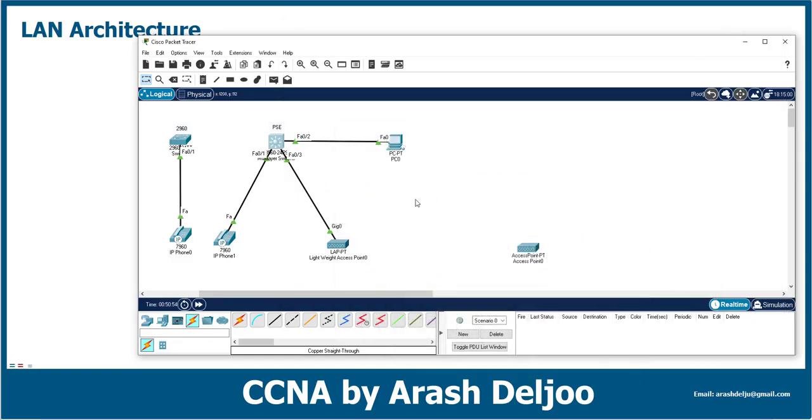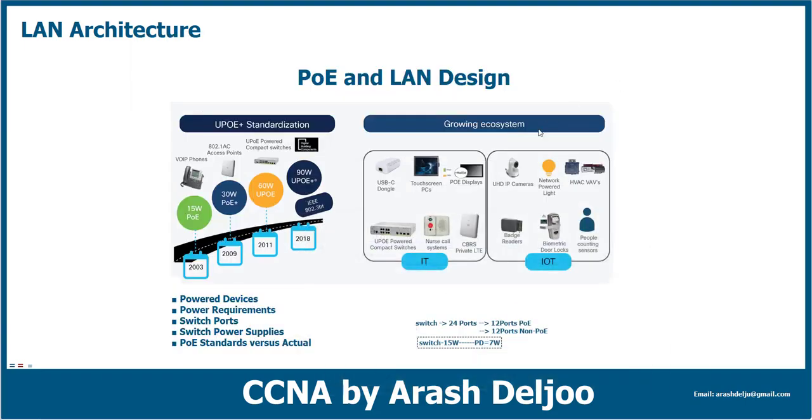Or maybe you have another device that needs a lower amount of power, and we don't have any problem, because the switch can supply lower power, but the switch cannot supply more than 15 watts on one interface. Don't forget, if you attach, for example, a device with a requirement of 30 watts to one interface, that device cannot work and cannot be enabled.